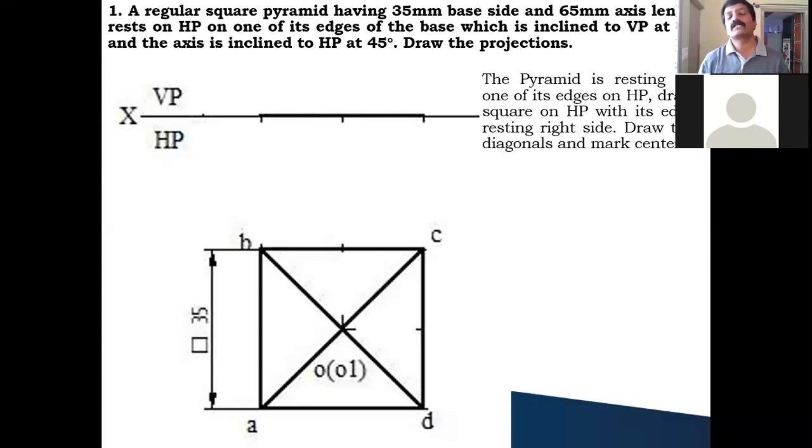So this completes your top view. You will see this square pyramid from the top side. It looks like a square, and the slant edges will look like diagonals. Even the diagonals you should make thick, as they are visible edges. So this completes your top view. Coming to the front view, how to draw the front view here? Draw the vertical projector like this from all the three points, that is from the center.